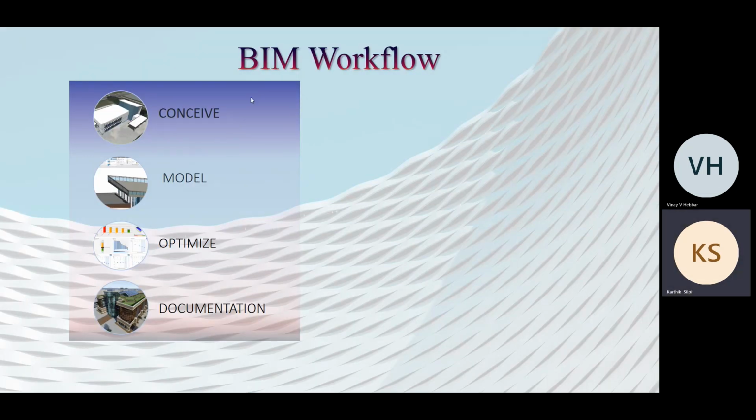So how does the BIM workflow happen? What is the start-to-end process? The first thing you have to do in BIM, as in any process, is to conceive the model. How is this thing going to look, a rough sketch or a detailed sketch. Then based on that sketch, you have to add more information to the model. Then for that model, we have to perform the optimization, which is clash detection, or if it is an HVAC, you have to perform calculations for equipment placement, and all this optimization takes place. Then after all the steps, we have to document. Documenting is nothing but preparing the sheets so that they can go to site. So this is the workflow: conceive, model, optimize, and document.